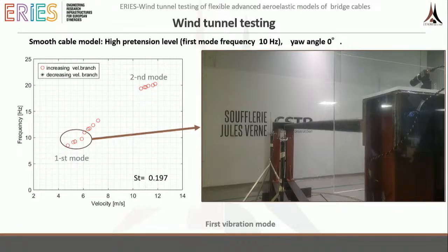Now I will show the case of the smooth cable with higher pretension level. The first part was about 5 hertz of the frequency. Here the tuning of the string was 10 hertz. So we can see the first mode here and the second mode. We didn't go up because it was too dangerous for the accelerometers.